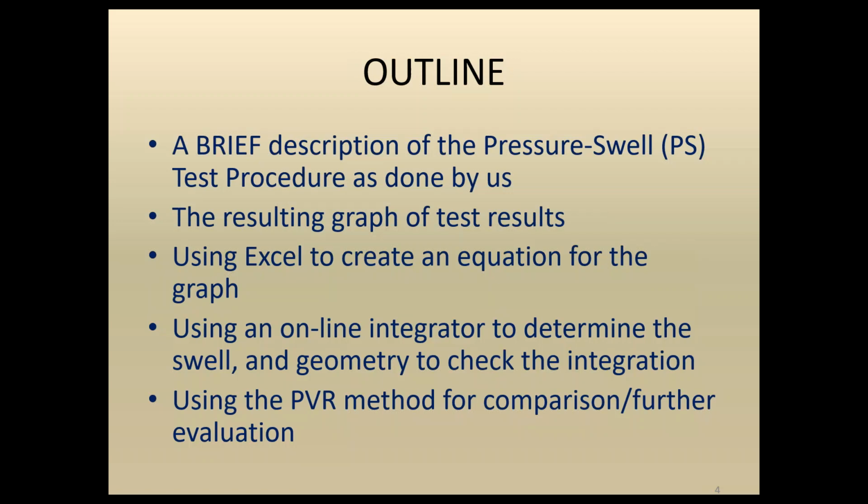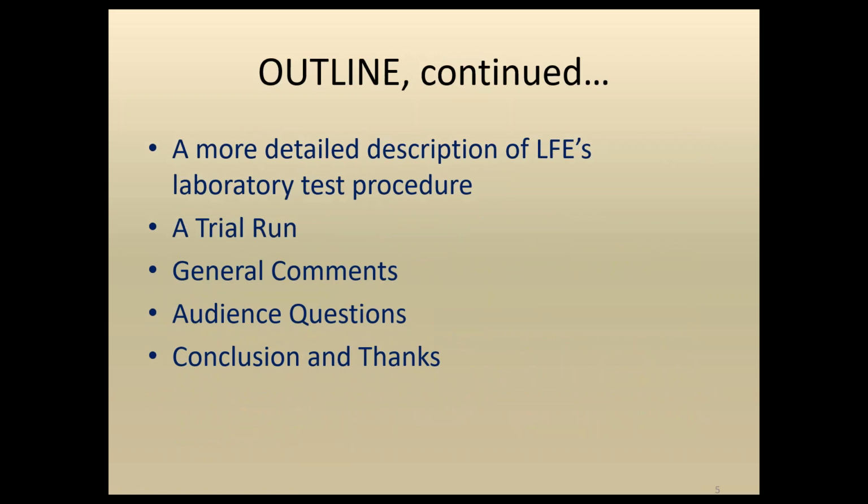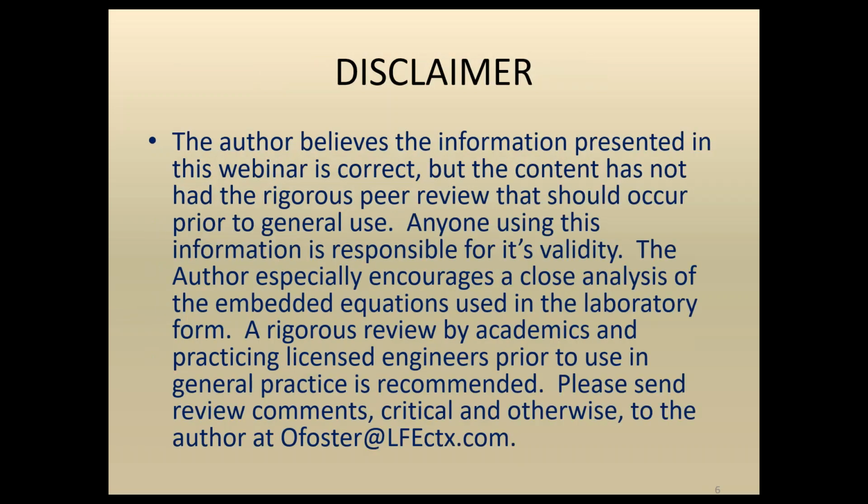So here's an outline of what we'll go through. We'll do a brief description of the pressure swell test as we conducted it here at Langerman Foster, the resulting graph of those test results, and then using Excel to create an equation for that graph, using an online integrator to determine the swell, and geometry to check the integration, and using the PVR method for comparison and further evaluation. We'll then back up a little bit and do a more detailed description of our lab test procedure, do a trial run, present some general comments, and then take audience questions, and then conclude.